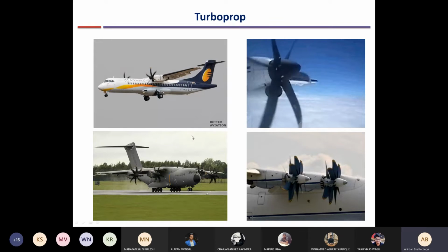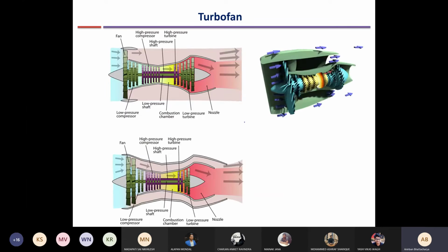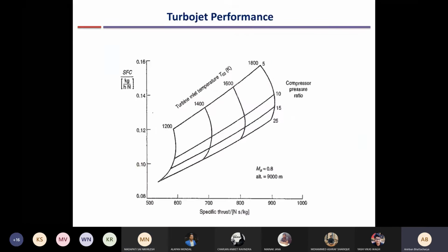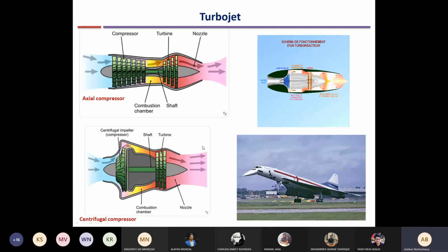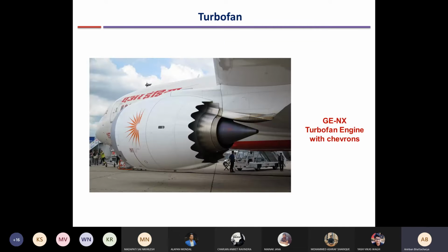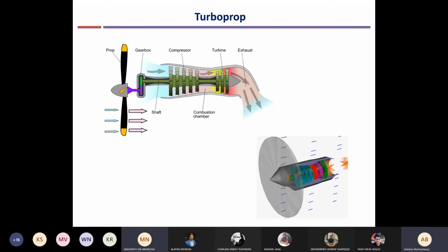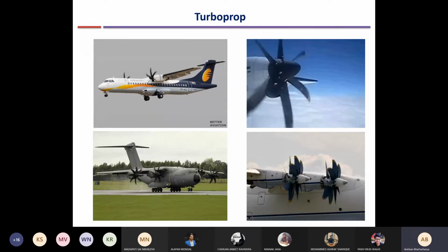If you take a look at IC engines, obviously you need to generate a very large amount of power, as compared to cars or automobiles, to lift an aircraft. So the engines will be of very large sizes, and their weights will be very large as compared to jet engines for the same amount of thrust. So the thrust to weight ratio is not favorable for IC engines. That's why they are not used. Jet engines also operate at very high efficiencies typically. So IC engines are not preferred. They are not used anymore in any aircraft. They went obsolete a long time back.